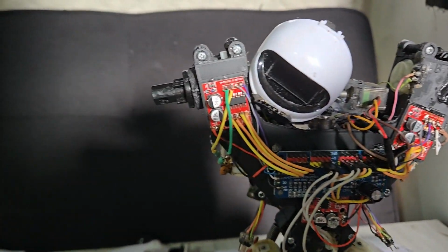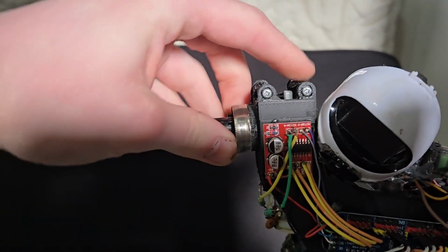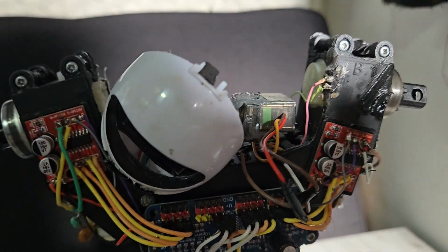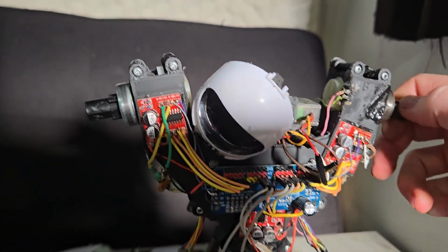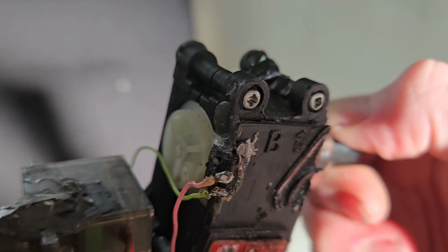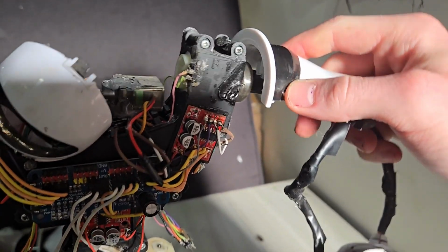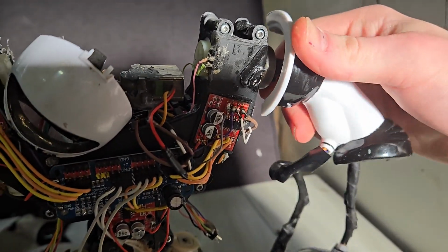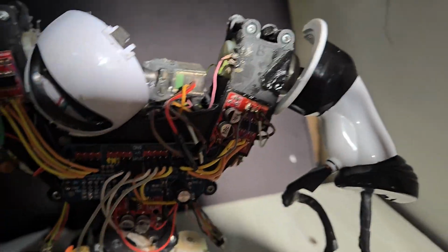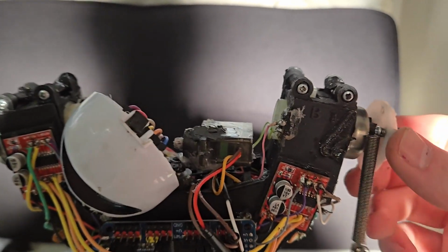So we'll install Robosapien's arm bushings back onto this third-party frame. It could take some persuasion. So we'll line up this bump with the limit switch, and once we do that, we'll go ahead and take our arm and put it on there. Like so, and that looks correct. It could take some persuasion, but once you get the arm pieces on, you can fit these springs over them.